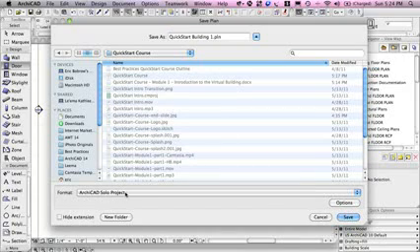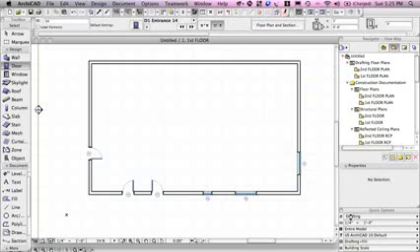It is going to be saved as a solo project, which means that it's a project that I can work on. Someone else could open it if I gave it to them, but it's not going to be able to be shared directly. ArchiCAD has the ability to share a project using its teamwork functionality, but we're not going to use that, of course, right now. We don't have to worry about any of the other things. Just make sure that it's named properly and it's put into a folder or on the desktop, wherever you would like, and then save. And you see that now it says Quick Start Building 1 here at the top.